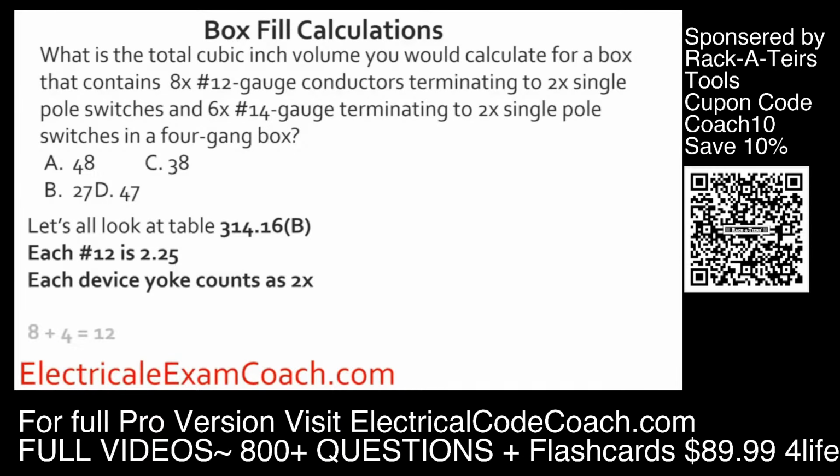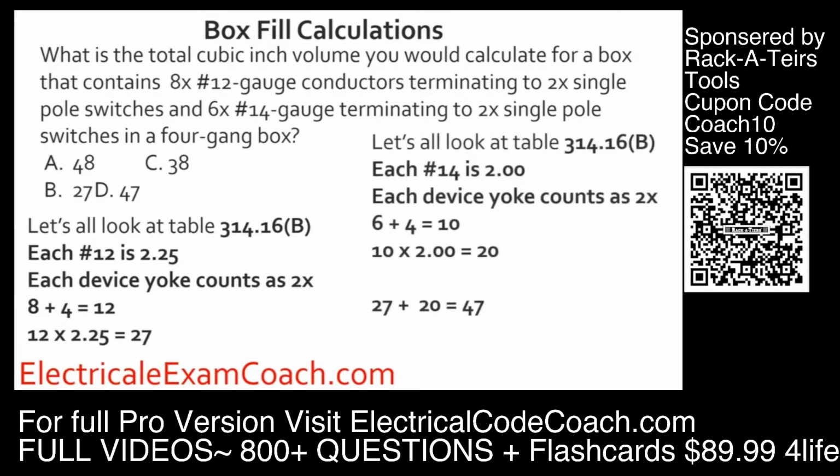Let's go ahead and deal with our 12s. We know that we have 8 conductors and 2 devices for those 12s, so each one of those devices counts as 2 more, giving us a total of 12 12-gauge conductors. We take and bear the math out, and we end up with 27 cubic inches. Now we just do the same for the leftover devices. We have our 6 original conductors, and we have 4 more based off of our count, because remember, it's based off the largest wire that terminates to that device. We take and bear that math out, total the two together, and end up with 47 cubic inches.